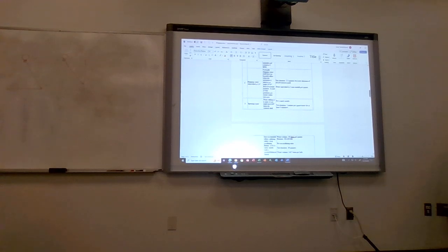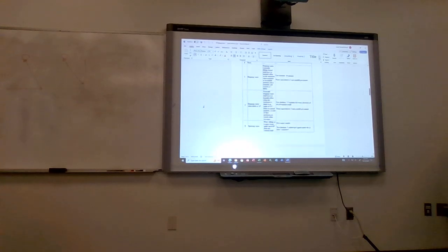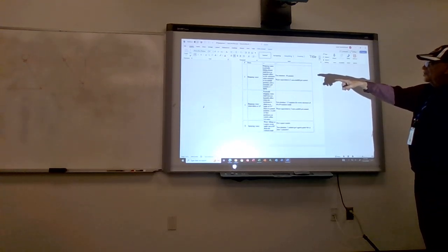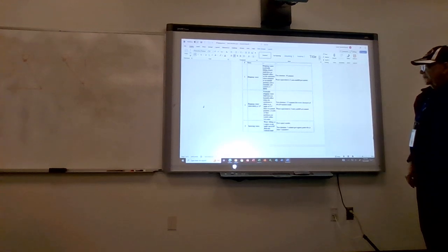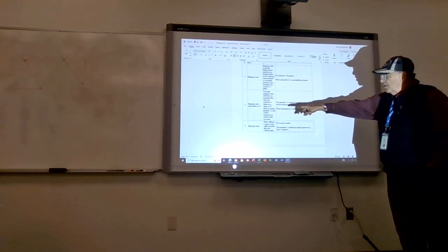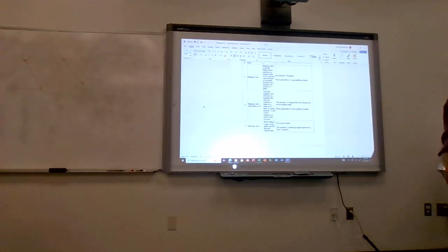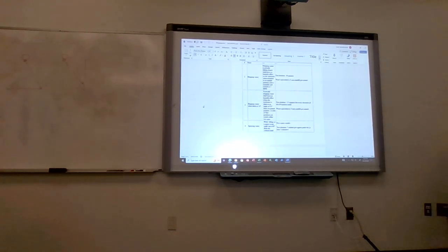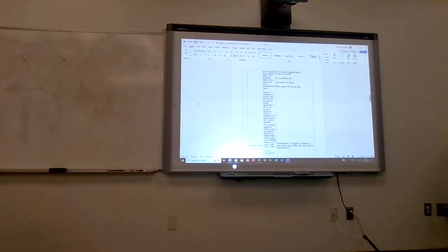The second number is the liquid penetration. I want to get this right. So, if an IP6 is followed by a 1, it means that it will resist dripping water. IP62 would mean it would resist dripping water when tilted at a 15-degree angle. Okay, IP63, we can spray the fixture. IP64, we can splash the fixture.